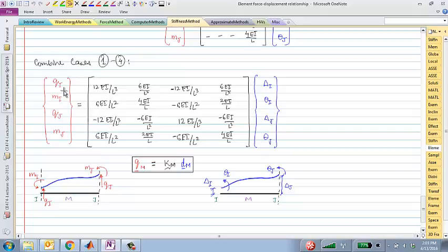All I did there was multiply KA times UA to get the 4 values at the ends of the beam element. Knowing these 4 values at the ends of the beam element, can you tell me what the shear force and the bending moment diagram would be?